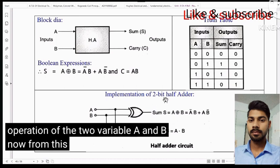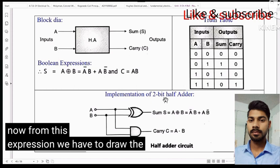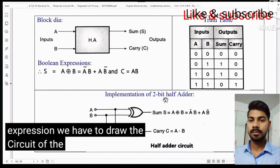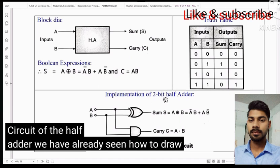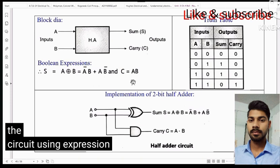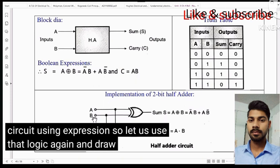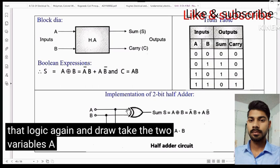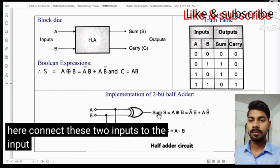Now from this expression, we have to draw the circuit of the half adder. We have already seen how to draw the circuit using expression. So let us use that logic again and draw. Take the two variables A and B here. Connect these two inputs to the input of the exclusive OR gate.